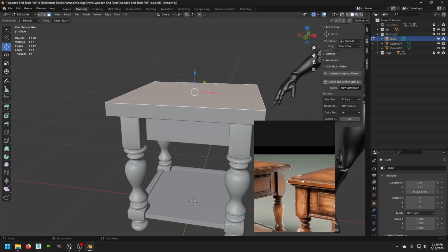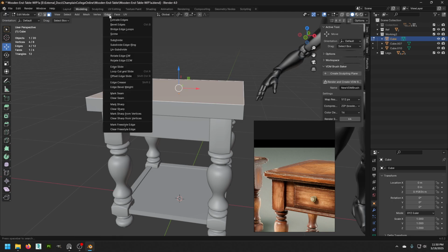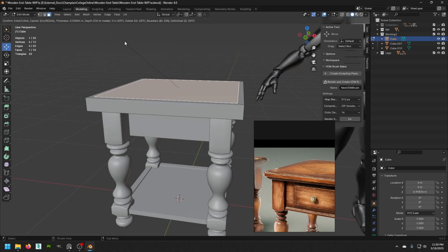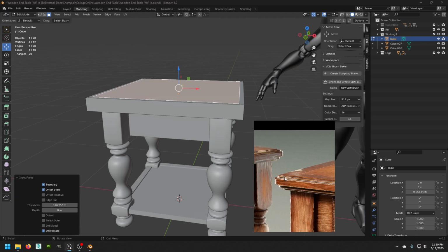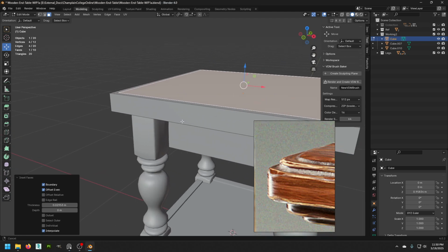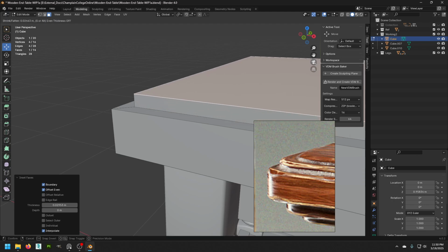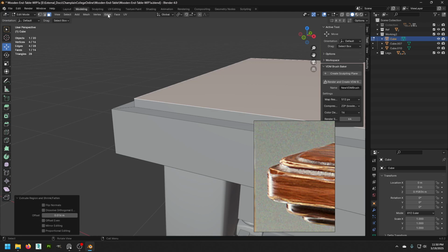Generally, we can look at this and do a general inset. So let's do face inset and then a little bit like so. Let's get this edge profile real close. We're going to do one, then go up along the normal, and then do another inset.